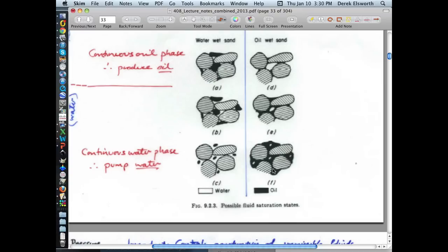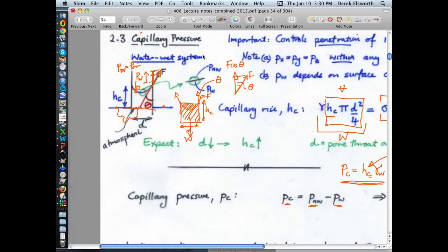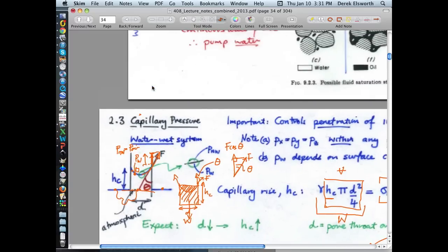We made the point before that most of the materials we're going to talk about in terms of aquifers are water wet. That means they love water. Water loves the grains, basically. Physically, a monolayer of water would love to cover all the glass that we have. In fact, that's the reason it's creeping up the side of this glass tube: it loves the glass tube and just wants to physically go up. It's hydrophilic, rather than hydrophobic.